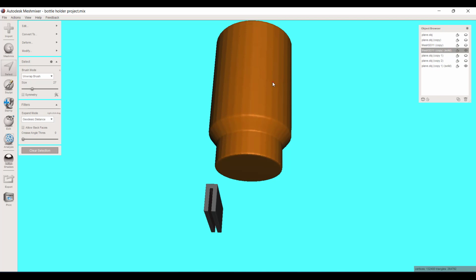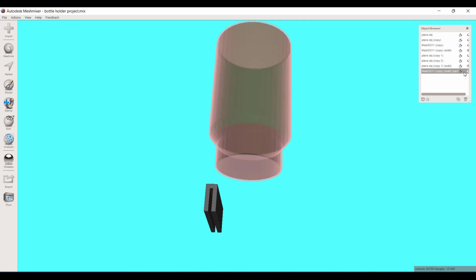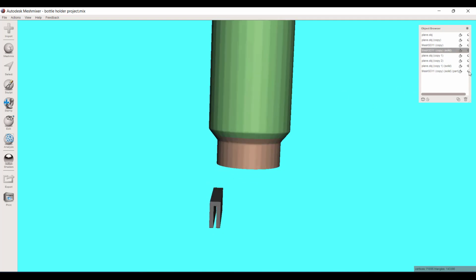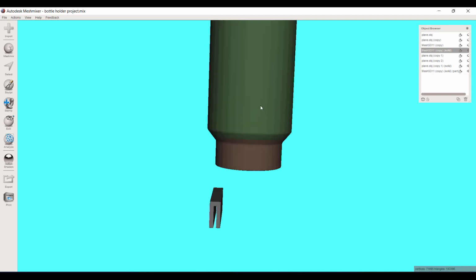which is helpful for us because we need to separate that off. All right, we don't want it to be one and the same STL as the bottle. So while it's still selected, you could either come to edit and modify. No, where is it? Oh, it is under edit, Separate, or you can just hit the hotkey Y. All right, now you see there's my original bottle. Here's my offset bottle. Original bottle, offset bottle. It's just 1.5 millimeters larger.